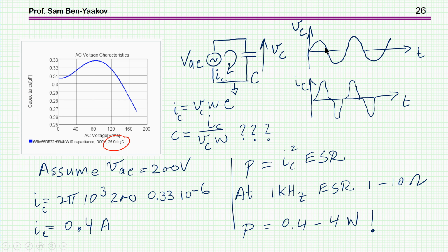Now you take this value and this value and you calculate from here the capacitance. Now, for the same frequency, this should be sinusoidal and this should be sinusoidal. However, here you have a distorted waveform, at least one of them. If, however, there had been a resistor here, this would also be distorted.